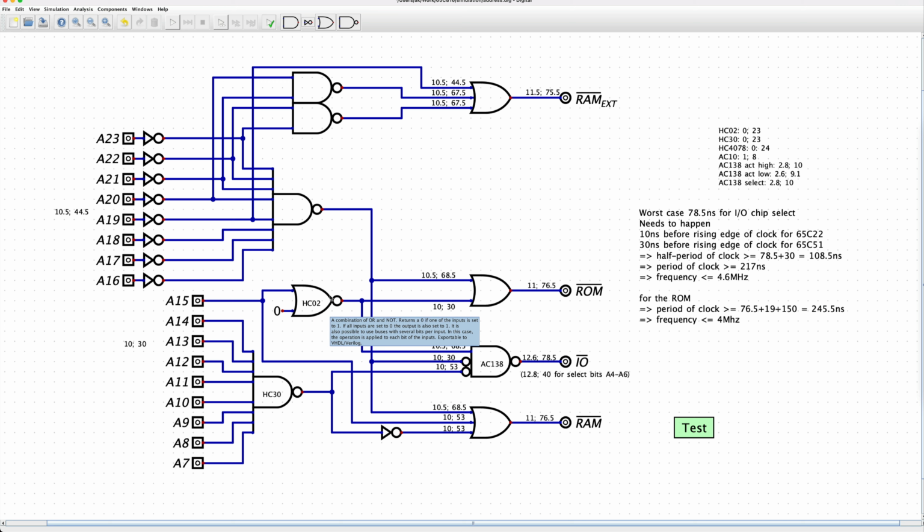Okay, so we have a single NOR here that we use for an inverter. But now we have NAND gates that we need. So I'm going to replace the NOR with a NAND to do the inversion. And we just need to change this to 1. And then this inverter we can also make an AND.